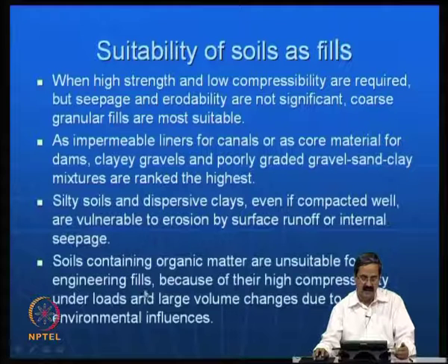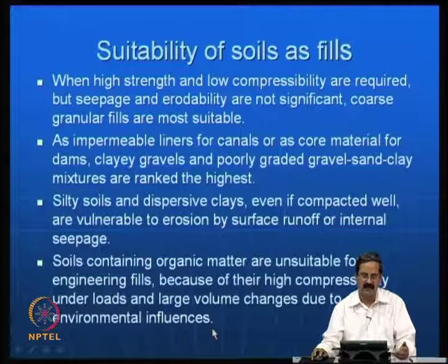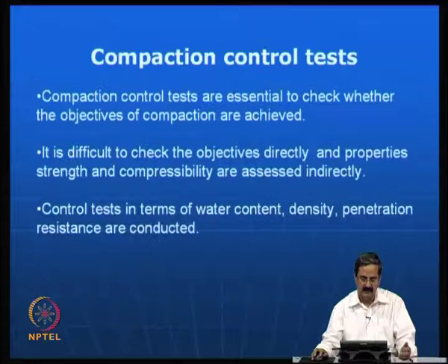And then there could be some soils which have a lot of organic content. They are not really suitable for engineering fills because of the high compressibility under loads and large volume changes due to environmental influences. So, some of these ideas one should have in mind, whatever type of dam or pavement or structure you are trying to think of. You must have some ideas in mind with regard to their general suitability, so that you can take a decision properly. This is very important.